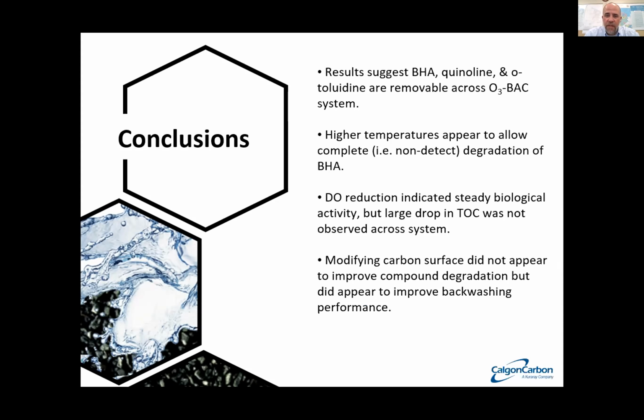One thing to tie into Lee's prior presentation is that we are going to look at PFAS compound removal through these systems. And they're not removable biologically. That has been very well established, that these compounds are, one, not removable by oxidation through just about any oxidative process that we currently apply, and are not removable, at least in current systems, through biological removal. But we would like to see how the physical adsorption of those is impacted by operating this system with a biofilm on the surface, which is going to be very valuable, since they're targeted for removal in water reuse, since we certainly don't want to add them back into our reclaimed water.